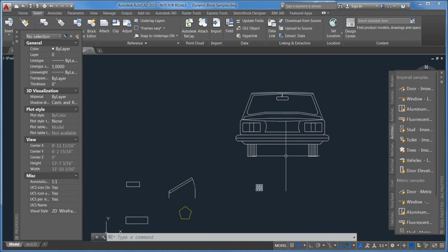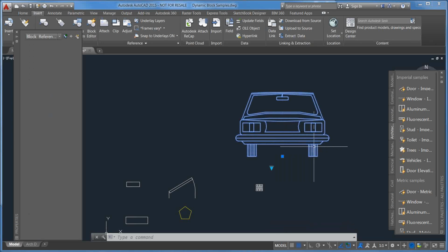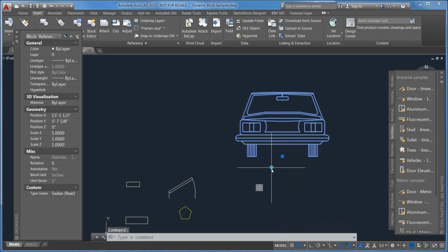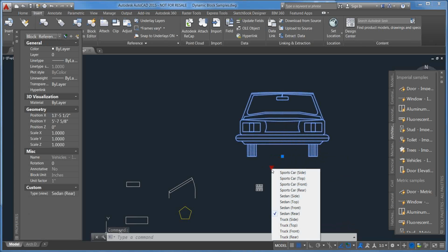All right, so Joe, hopefully that gets your question. Mike has a kind of a dual question here. Does the AutoCAD file store all of the states of the blocks in the file? And then he comments that could make the file pretty large. Good point. So yes, when I click the list, I see there are 12 different visibility states, and AutoCAD does store all 12 of those states.